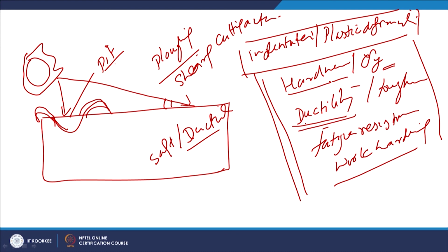A wedge is formed as per the shape of the particle which is impinging. But if continuous deformation of such material takes place, then it will get work hardened and eventually it will be removed. But the removal of the material is less if the soft and ductile workpiece material is subjected to high angle impingement, meaning erosion by particles impinging at a high angle.